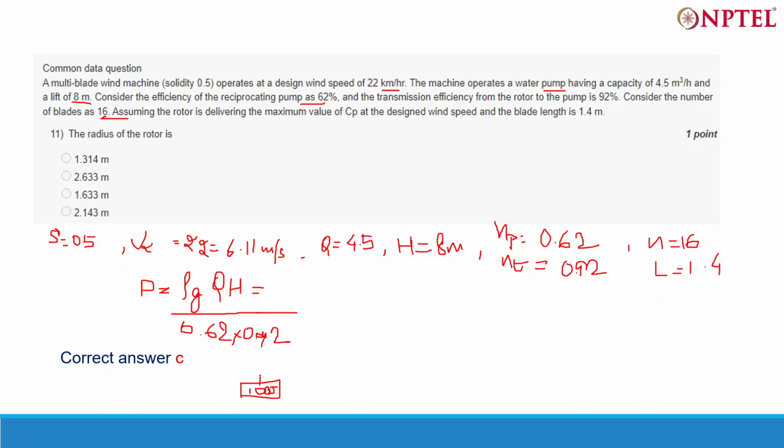But there are some losses also, because efficiency is less. To cater for these losses, let's say overall efficiency is 0.5. So if I give 100 joule of energy to this box to do the work, it will only transfer 50 joule. So I will divide the 100 by 0.5 and give that amount. I will give 200 joules, 100 joules will be lost, and 100 joules is directly transferred to the box. So similarly in the pump also.